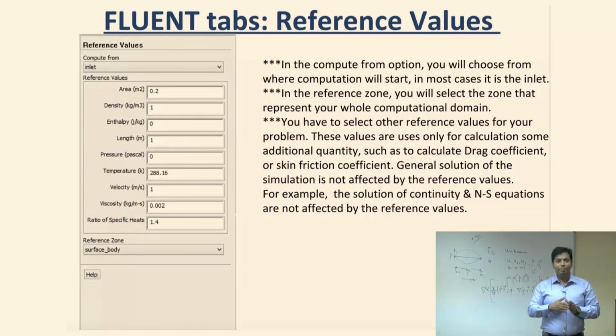For example, if it is time dependent, from 1 to 10 seconds, and you want to get a curve, every time step it is calculating the Nusselt number, but if the temperature is not correct, it is not giving you the correct solution. So the reference value is important for your post processing. It does not do anything with your simulation results. I think that's it.